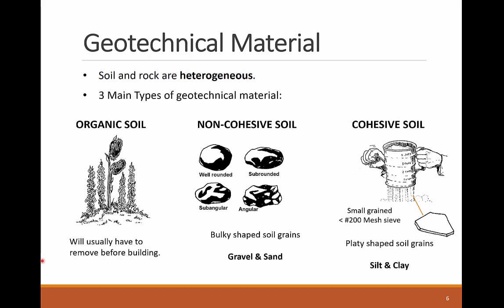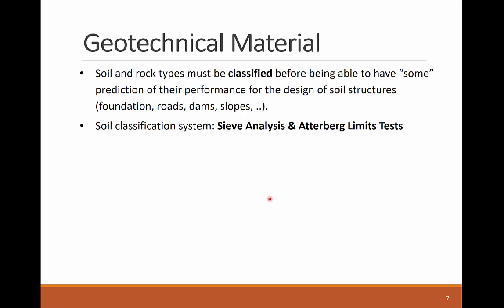However, clay consists of very fine microscopic plates, like these plate-shaped particles, which hold water to increase their volume and release moisture to decrease their volume. So, special precautions need to be taken in the design of footings to resist or avoid the forces caused by shrinking and swelling of underneath soil made majorly of clay and silt.